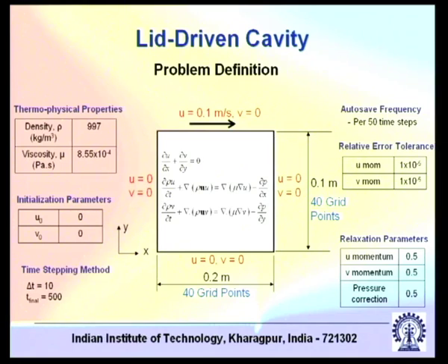Where you have strong gradients in variables, there you have to cluster fine grids, and where you do not have strong gradients, there you do not unnecessarily keep fine grids, you can keep coarse grids. But the art of meshing is that you do not suddenly jump from a fine grid to a coarse grid, you go through several transitions, because a sudden jump can make the system of algebraic equations being solved unstable. So there is a relationship between the nature of meshing and the nature of the algebraic equations that get generated out of it. If there is a variable meshing, one has to have it graded: a refined mesh at locations where you want to capture strong gradients, and coarser mesh where you do not.